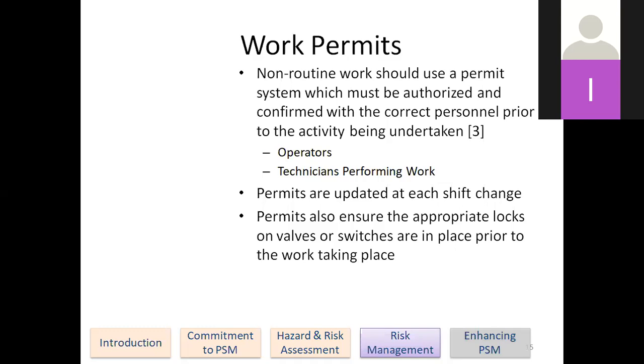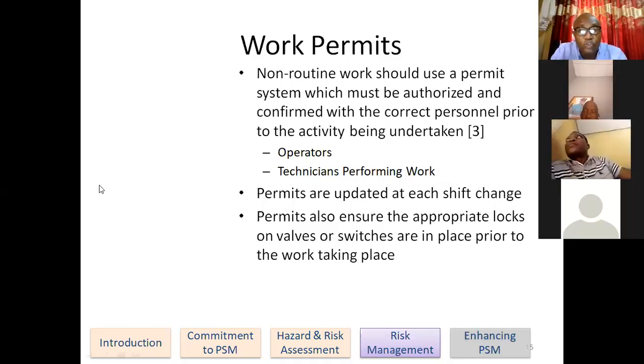And permits are updated at each shift. Don't say because I gave permit to Mr. Ade last week and he's coming to do this work again this week, I won't give him permit. He had permit last week. No, you don't know the condition he is coming in this week. So you need to do the checking again to confirm that he is in a safe position to do the work.